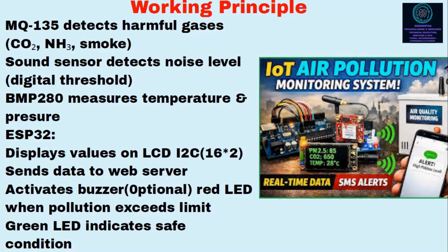And instead of using the common DHT11 and DHT22, I've used BMP280, which measures temperature as well as pressure. It is all connected to ESP32. A display is also there, a 16x2 I2C display.